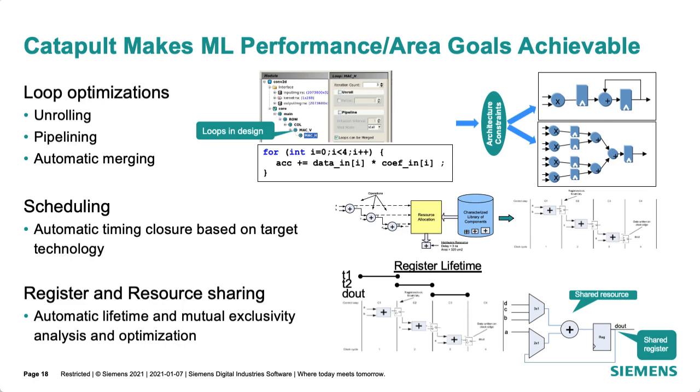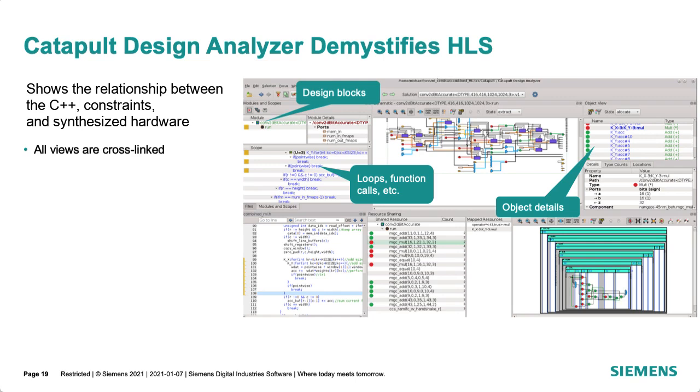Register lifetime analysis is performed automatically, and the tool will automatically reduce and share both registers and resources based on the design's performance constraints. Designing using high-level synthesis is not just taking C++ or SystemC, throwing it into the tool, and getting out RTL without knowing what happened.